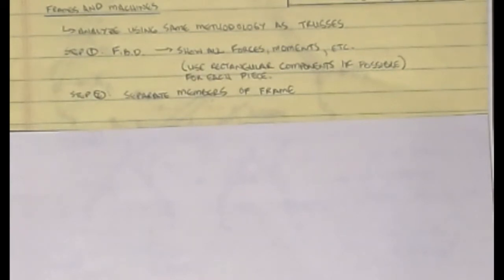Okay, the first step is always drawing a free body diagram of the entire system. We're not going to blow anything apart, because that keeps us from exposing internal forces at the time, and maybe we get lucky and maybe we can find some of the support reactions. It's not always the case, but we want to try to find what we can without going into any of these more complicated methods first off.